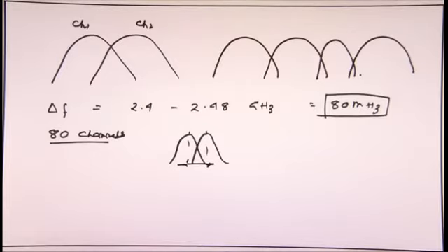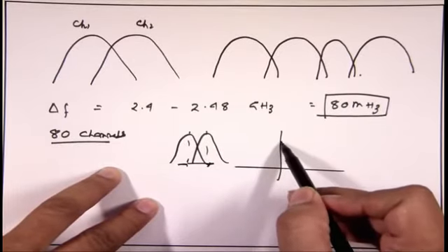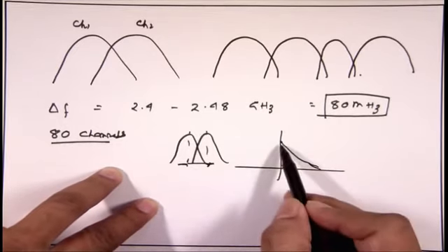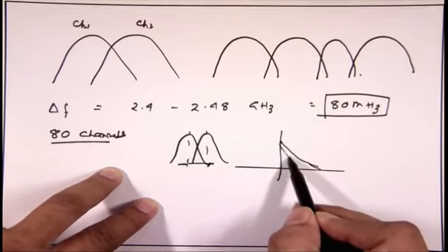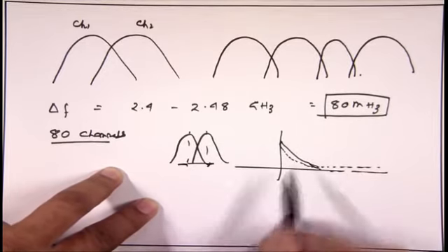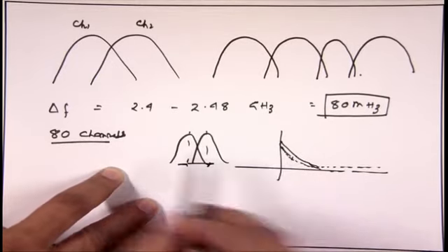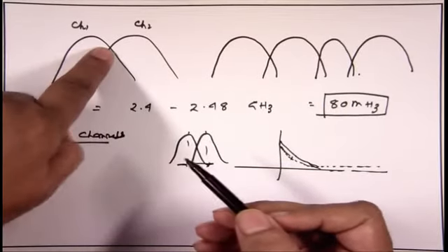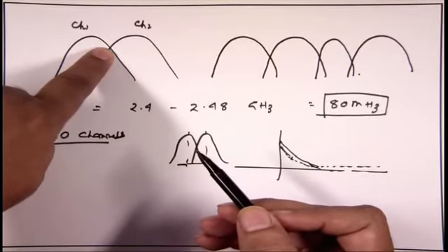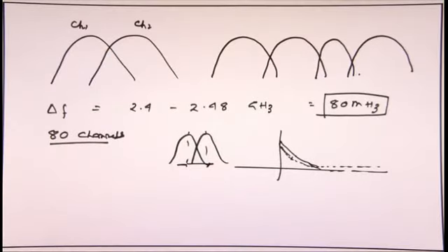But look at the signal. The signal will be like that. I am showing only a single side. In that signal, you will have what? It is superposed with some sort of phase noise. This phase noise will add with the signal, and the superposed signals of the 2 adjacent channels with the noise will blur your resolution.